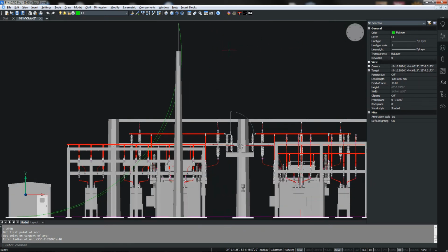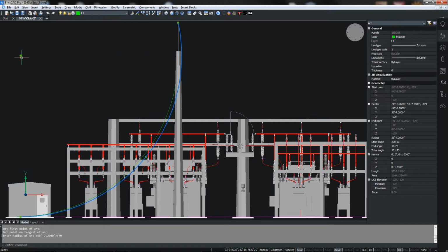Now you can see why I mentioned we should make this the height of the pole, what we did. If we look back at this, here you can see we're looking down the line from the static mast back to the drop-in pole, and if I select this arc, you can see that the center of our arc is actually below the top of the pole. So if you can picture this sphere rolling toward this static here, the sphere will actually have to roll underneath the static